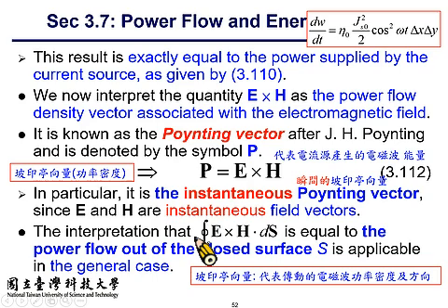So if you define a closed surface that is enclosing the whole dipole antenna, and do the calculation of the closed surface integral of the Poynting vector, which is the cross product of E and H, you can calculate the power emanating from this closed surface.